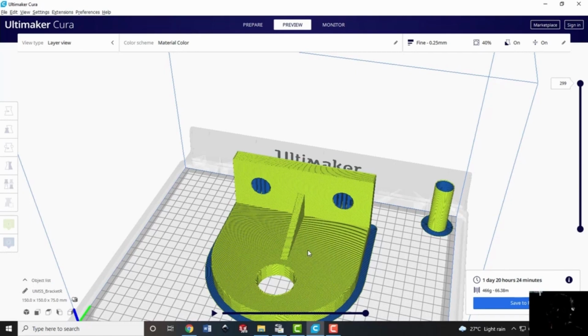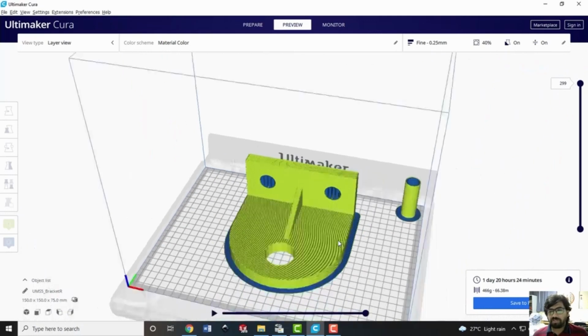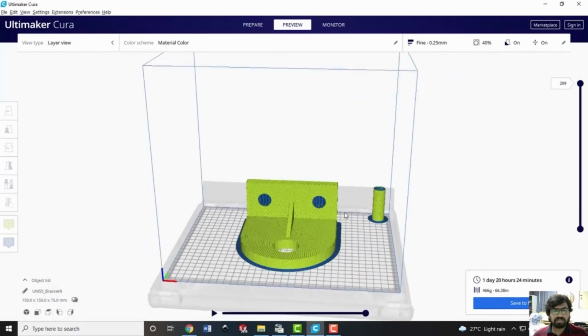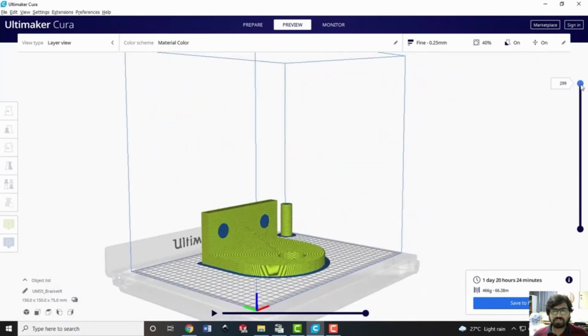However, of course, there is no large force we are applying, but due to the viscosity of the material itself, some drag is always there on the part that tries to move the part in the XY plane, which is undesirable. Because if it happens, then you may deposit the layers in shifted manner and you will never get the part exactly what you want. So now let us try to see the different layers and we will do the simulation as well.